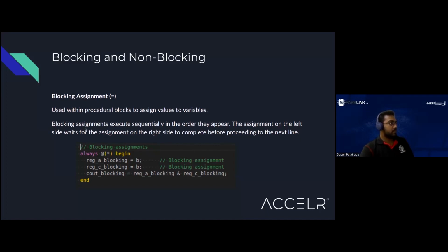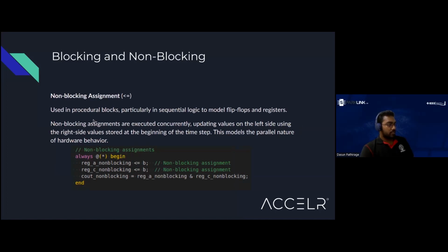Okay, so non-blocking. This is mainly used when we are designing flip-flops and registers. So for sequential modeling, we use non-blocking assignment.